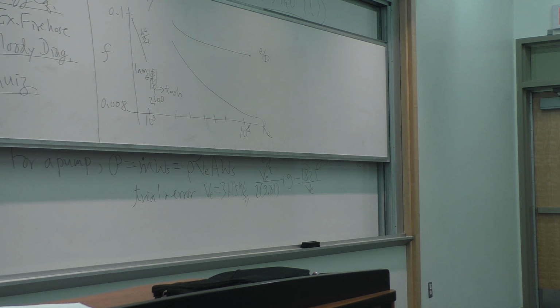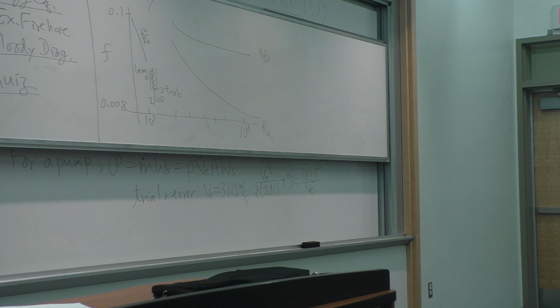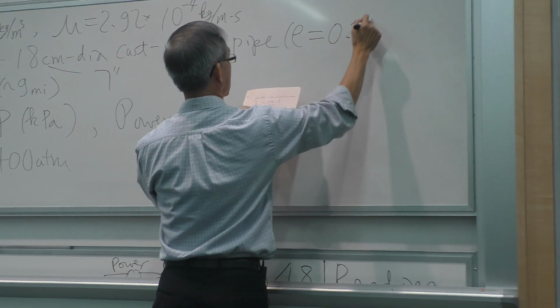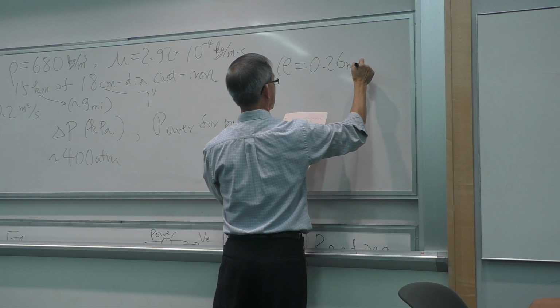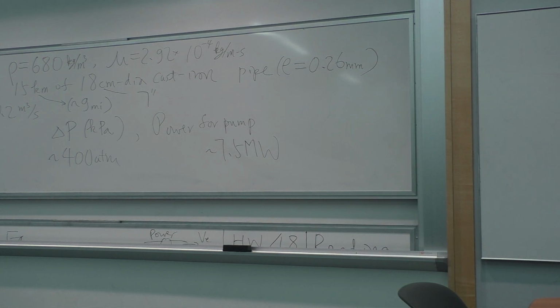Once I told you what pipe it is, you can look it up from the manufacturer on those pipes. They will tell you that, for this reason of using the Moody diagram. So cast iron pipe, the roughness is approximately 0.25 millimeter, and it changes as the pipe gets old.